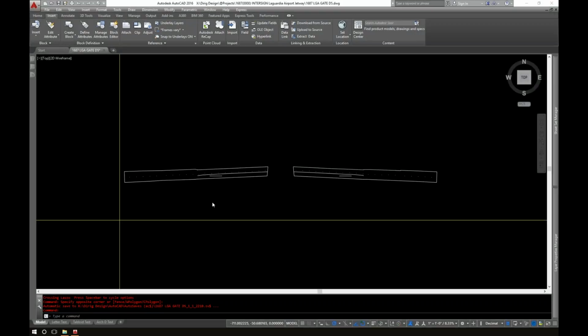Alright, I'm going to finish the second half of this video. In the first half I took the 3D geometry created by the 3D Disto and flattened it into 2D, which is what we see here. Now I'm going to take this 2D information and create the wall paneling that we were after in terms of the measurements. I'm just going to walk through the steps of this.